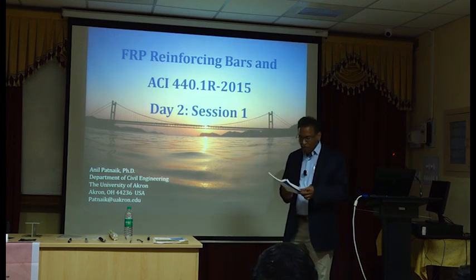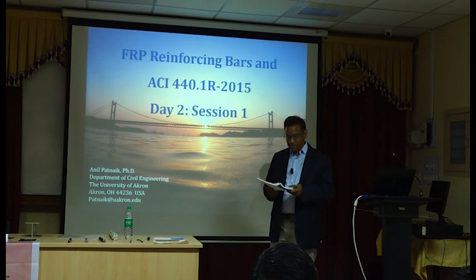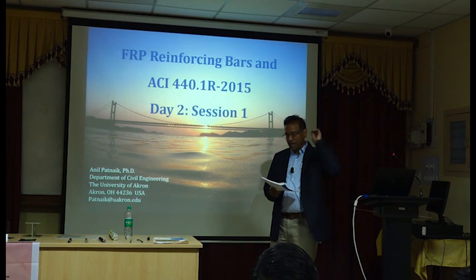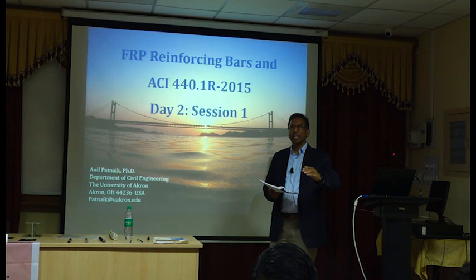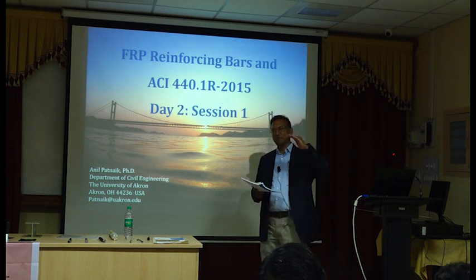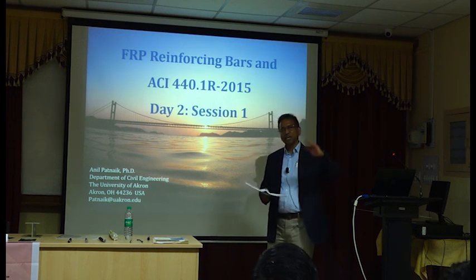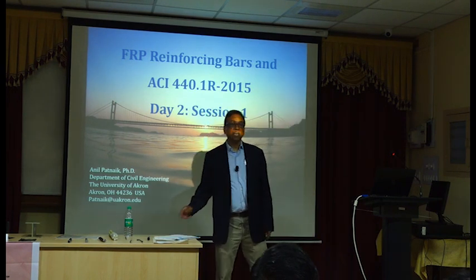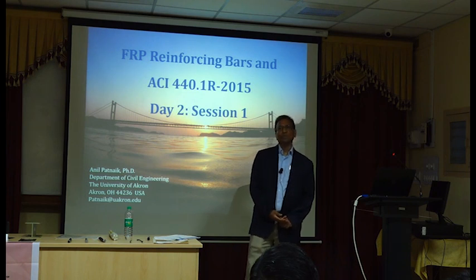ACI Committee 440 deals with FRP materials. It has a state-of-the-art report, then internal bars, then external reinforcement, and then they have test methods, pre-stress concrete. There are so many different kinds of documents. If your library can get those documents for you, that would be very good.